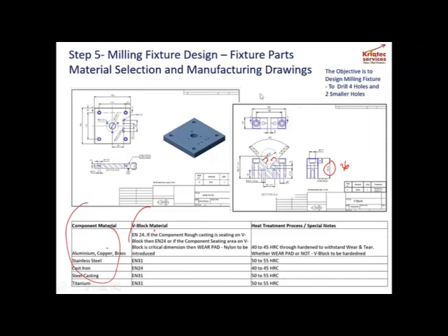The detailed drawing plays the major role, because the part has to be manufactured. Therefore, the students or whoever is undergoing fixture design, the basic fundamental principle is they should know dimensioning, they should know about GD&T, tolerancing, limits, fits. If you look here, I put 25H7, and in the same way the mating part I could have done as G6. All this you should know.